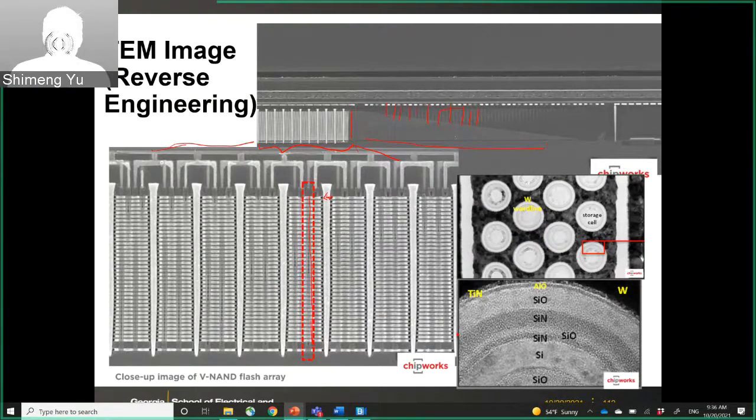And if you look at the top view, if you really zoom in, you see a whole area, and then you etch through that hole, and then we fabricate this kind of core-shell structure, as we discussed before, right? So here in the core, you have silicon dioxide as a core, and then you have the polysilicon channel.